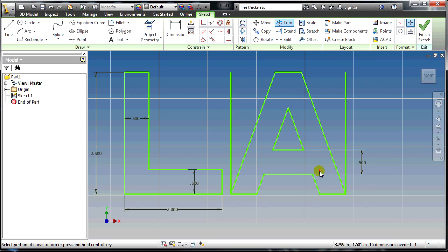For a lot of these diagonal letters, I would recommend building a box first and then building the letter inside of the box. If you noticed, some of these, when I deleted this bit, it got rid of the dimensions. They are still correct, but if you drag these around, it can change those. As long as you can see the dimension, it's going to be guaranteed to stay the same. If you do not see the dimension, then it can change in the future. So you can put some of those back in if you like.